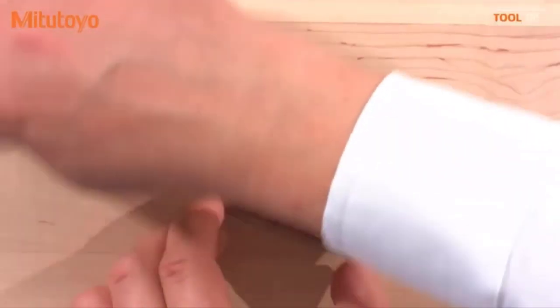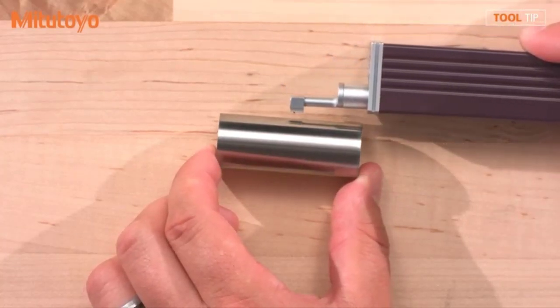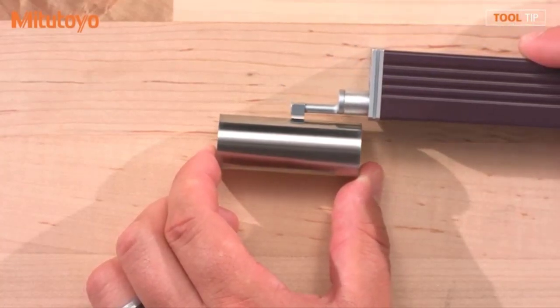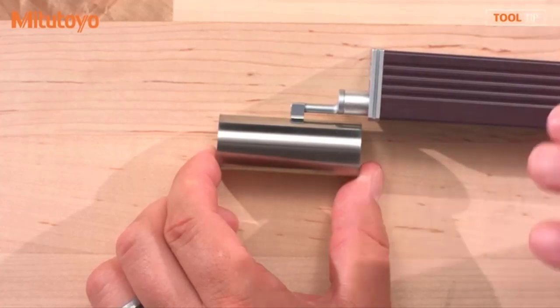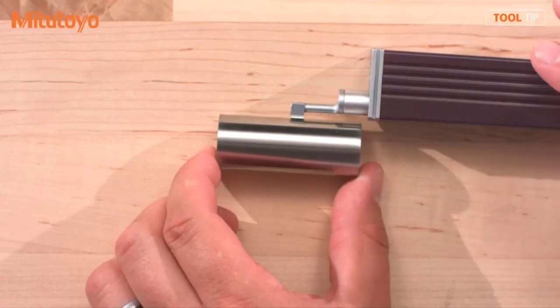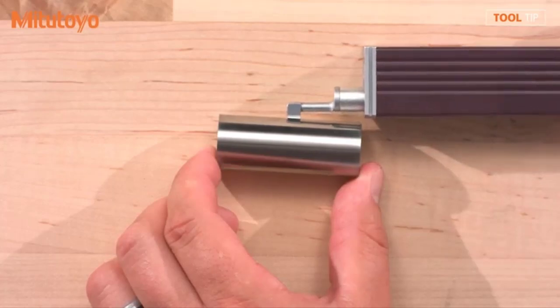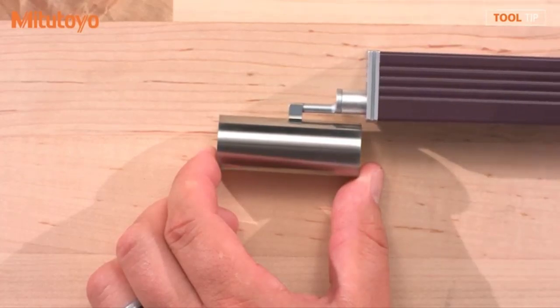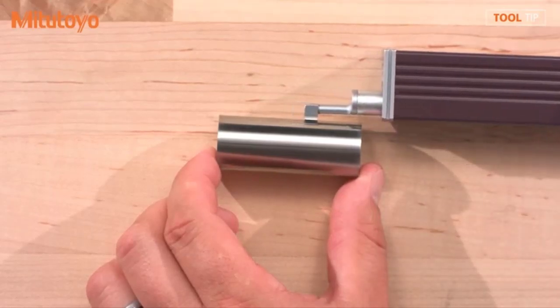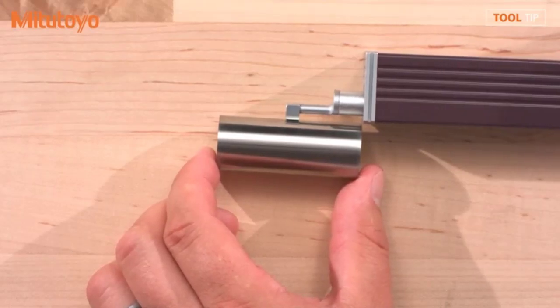If you're measuring along the axis, a skidded unit would be great, because what's important with the skidded unit is that after it makes contact with the part, the skid is always in complete contact with the surface being measured. If you look at the skid here, there are no gaps between the skid and the part anywhere. It's nice, even contact, so if I move the stylus or the skid back and forth, it's always in contact with the part. That's important because the skid is the datum, and if the datum isn't making good contact with the part, you get inaccurate measurements, right?